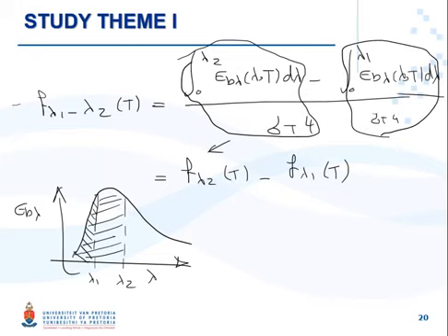Again, that's the definition of the blackbody radiation function, and we divided it into two different terms. So that shows how we can use the blackbody radiation function to calculate the blackbody emissive power without using complicated integration.